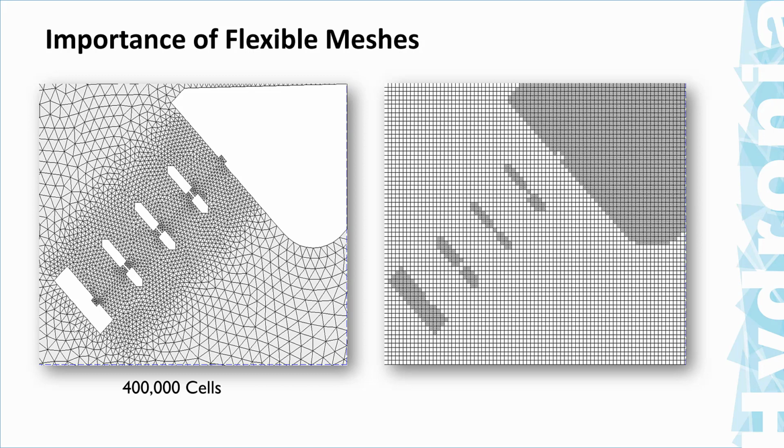So in this particular case, we were able to generate a mesh that covers everything with the adequate resolution that was required around this structure with 4,100 cells. Now, the same mesh or grid in this model would have required 2.2 million square cells. And that was much more expensive from the computational point of view than this one. So that's one of the advantages of flexible meshes.